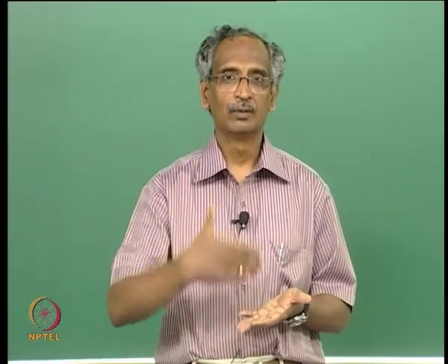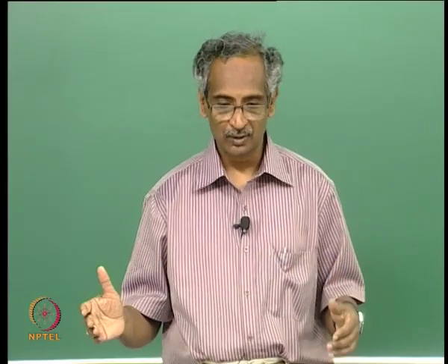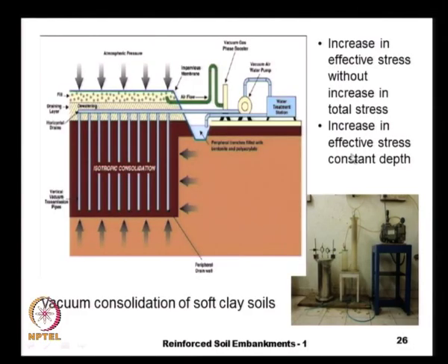The stress is more in the vertical direction compared to the lateral directions, and because of that we generate shear stresses, whereas here the vacuum being an isotropic stress, there is no generation of shear stresses. On the right hand side bottom you see a small example of a laboratory test being performed to achieve the vacuum consolidation.